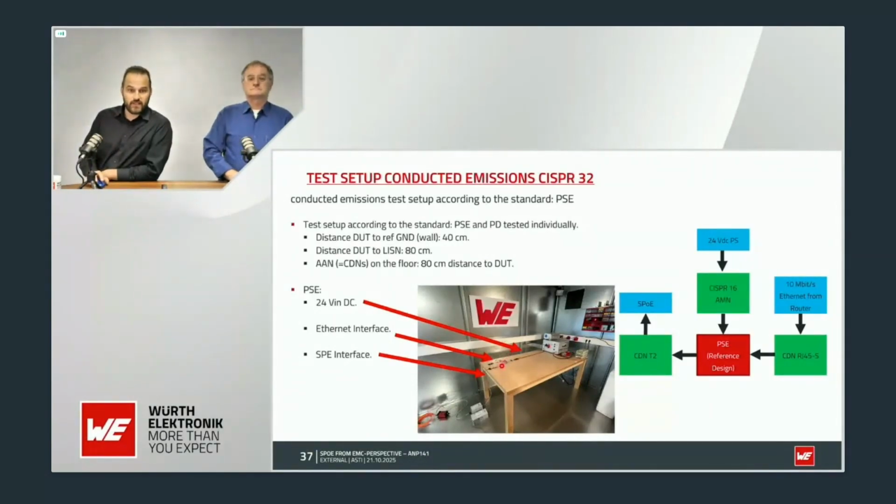Why are we doing that? I would assume that we would also pass the limits and the tests for when we connect an external AC to DC power supply, at least for this electronic circuit, when we pass the same requirements with the DC input. So more or less, we assume that our power supply will not filter what is coming from our board.